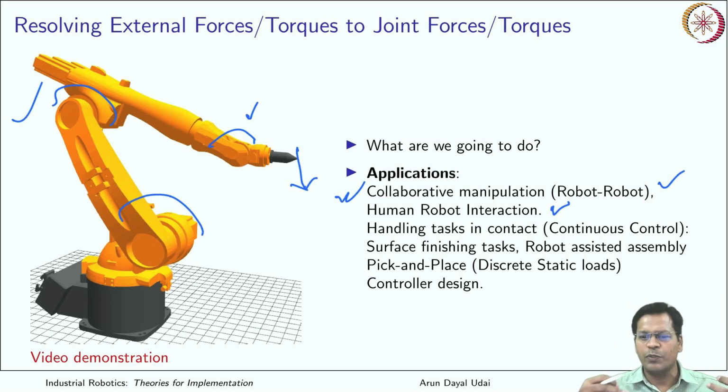There are many contributions to torque. The first contribution is due to gravity. You have to compensate against gravity, so that torque is fed to the robot so that it can maintain its position against gravity. The second one is to do some kind of job, that is, to take care of the external forces. So this is the one which is the external force. There are many other torques as well. One of them may be to move the robot in space with certain velocity and acceleration. Those are the different kinds of torque which contribute to the total torque which the actuator generates to do the whole amount of task which a robot normally does.